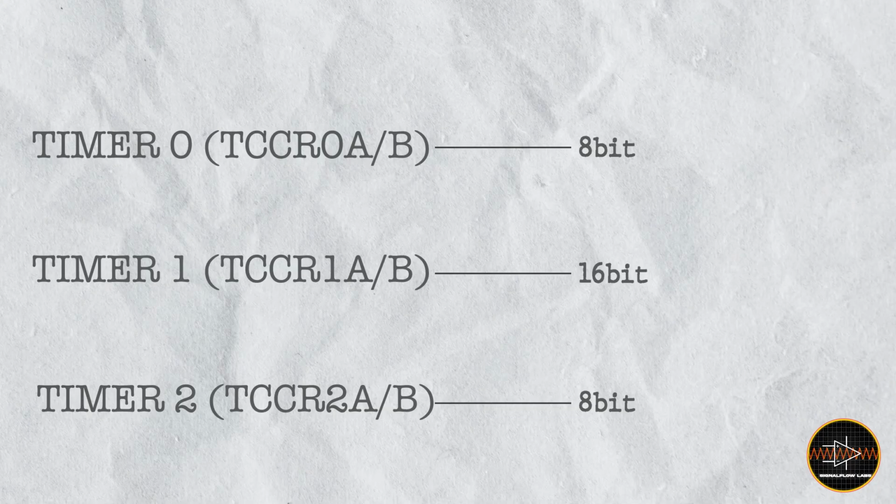Timer 0 is used basically in functions where you want to put a delay into the code, such as millisecond delay, 1 second delay, all sorts of delay. Timer 1 is used for precision control of servo motors, when you want to control servo motors or similar devices. And timer 2 is basically used to count interrupts. If I have a code in which I have to count the number of times it was interrupted, or the number of times it detected a value, that's when we use timer 2 and initialize it.